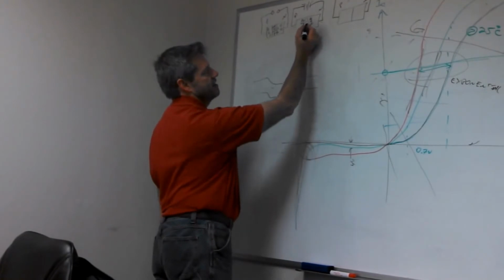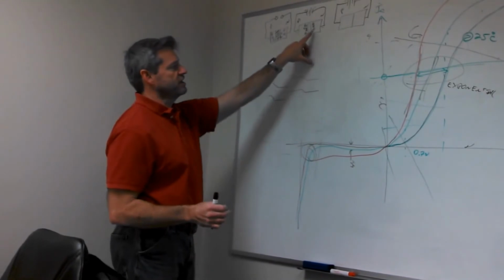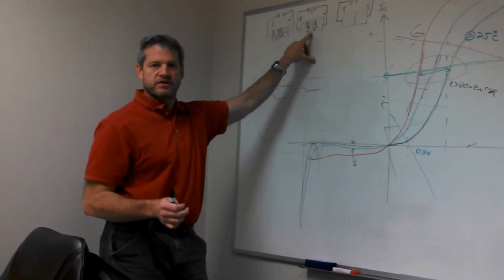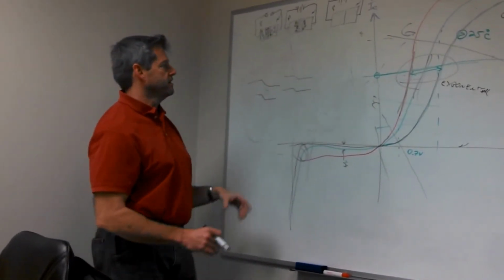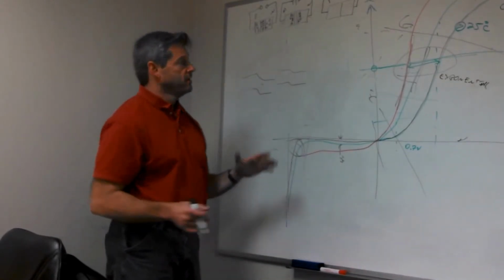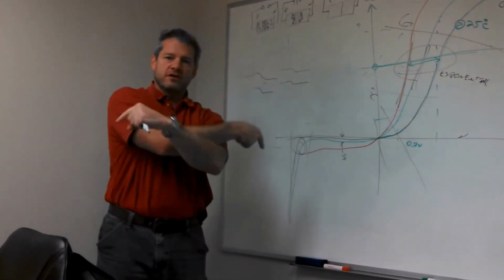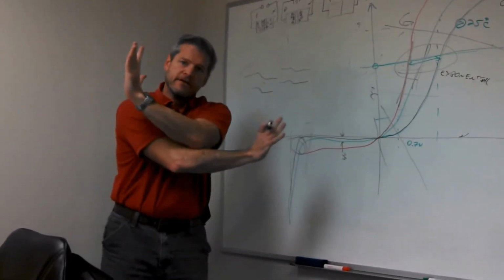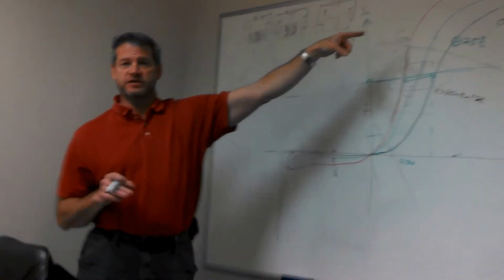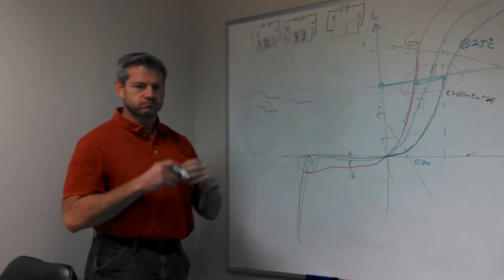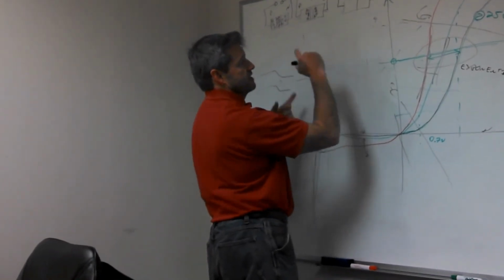And if I forward bias it enough, then these guys are just going to jump right across and bang, they're going to go because their diffusion length is longer than this depletion region. And so they can diffuse across and go. And if I keep forward biasing it enough, we effectively, conceptually squish this all the way flat where there's almost nothing there and everything goes across. In fact, if we put a big enough voltage across it, push them the other way and then bad things start to happen. You're getting up into this ohmic region, and eventually you're going to burn the thing out because the heat's going to... In the reverse bias region, you've got exactly the opposite, right?